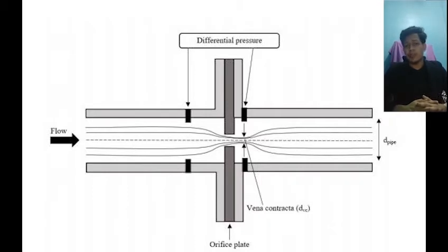Based on the picture, I'm taking the orifice plate as one of the examples that are considered non-radioactive technology, because there is no involvement of radioactive material in the pipeline. Okay, how does an orifice plate work? We install an orifice plate in the pipe, which causes disturbance of flow, and then the differential pressure can be obtained by using Bernoulli's equation.